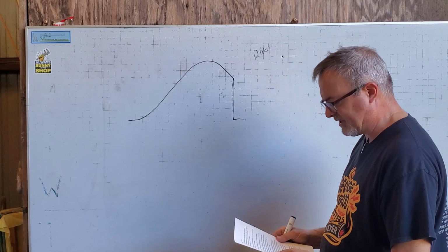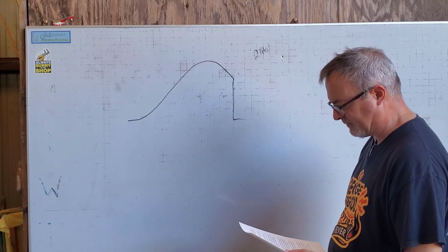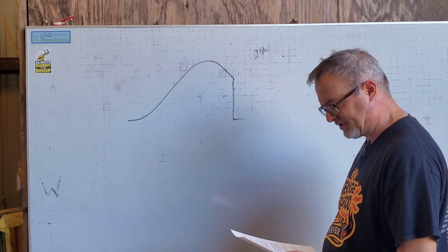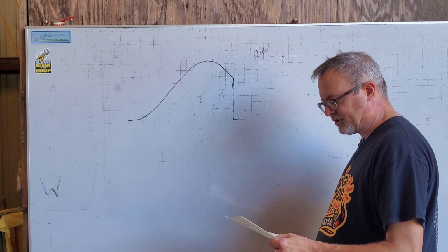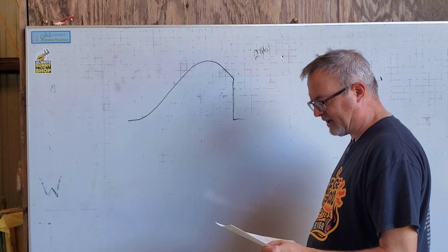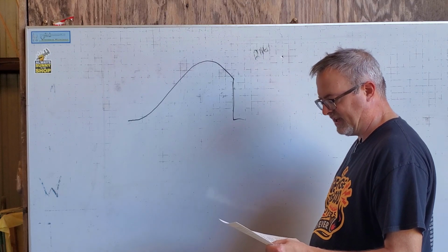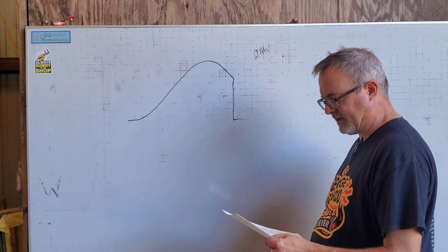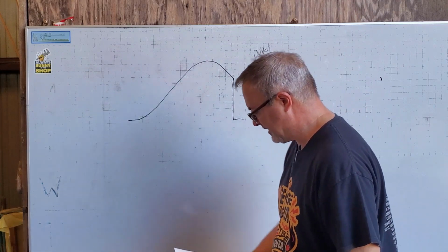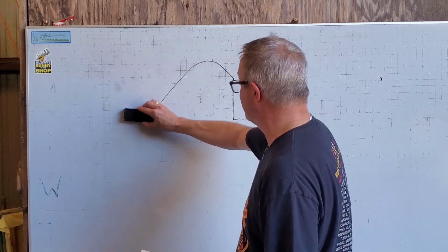Number four, balancing a steam engine is a trade-off between balancing the vertical forces and the horizontal forces. The connecting rod creates a vertical force because one end of it swings up and down. The piston, rod, and crosshead create horizontal forces, and I think part of the connecting rod weight does also. The crank pin creates an unbalanced force as it rotates. All of that is true.